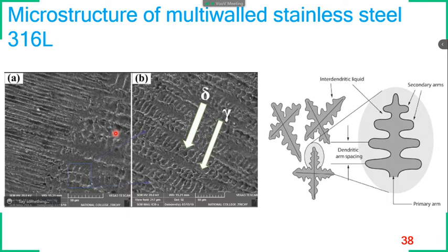Right now some research has been carried out in a positive direction, and they have even achieved very fine grain size by opting for various strategies in WAAM technology, which we will discuss next Friday. We will be discussing how we can minimize the grain size. All these things will be covered. But generally in the as-fabricated condition, we can expect a coarser grain in wire arc additive manufacturing, because it takes more time to solidify.